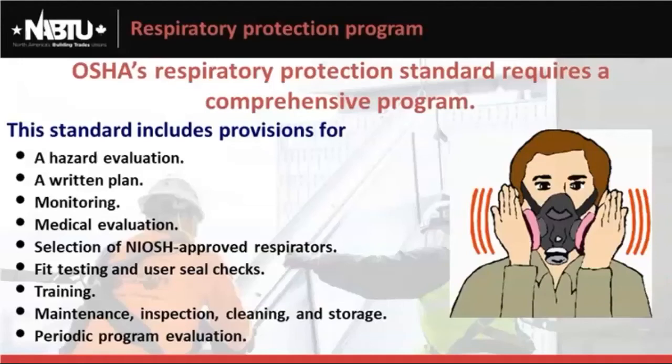Okay. In addition, because we're dealing with silica dust and a lot of those operations require you to wear a respirator, the contractor is required to make sure that anybody that's going to be given a respirator has to have a medical evaluation. Okay, that's pretty big. You have to make sure that the employees are fit tested and medically cleared to wear a respirator.